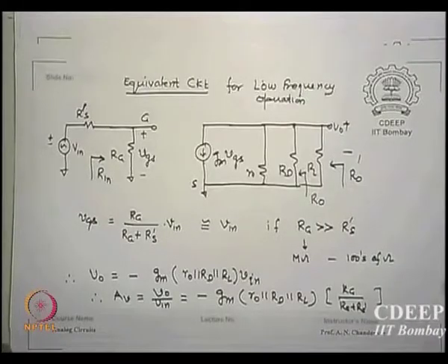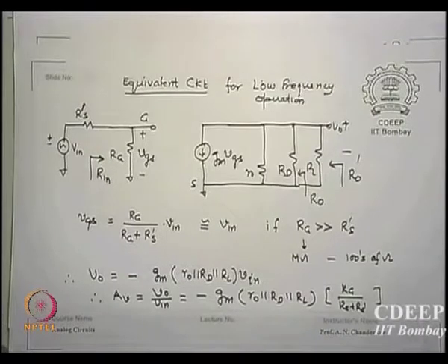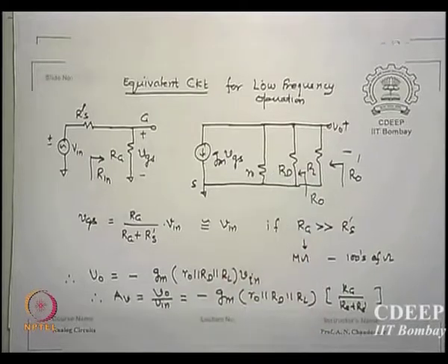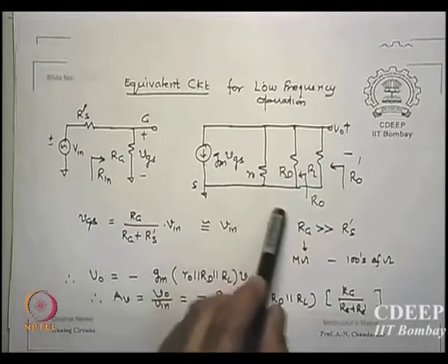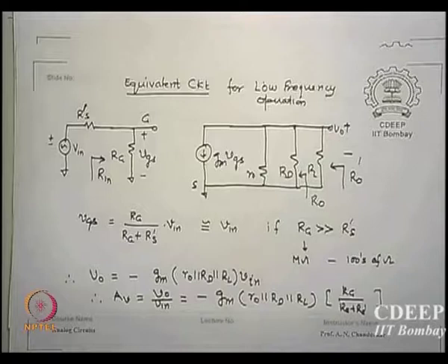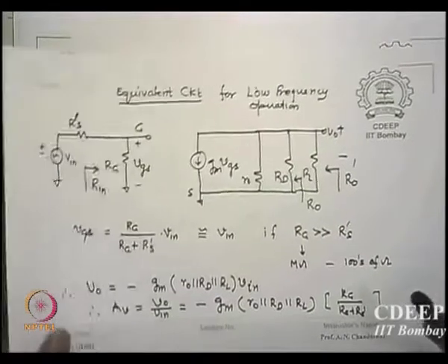Normally RL is not considered to be part of output resistance. Why? It is external, I do not know what people will give me. So normally R0 is taken across RD. Even some people believe you should measure intrinsic R0 also, that is without even the drain resistance. Is that correct? So it will be always R0 in most cases. Okay, so if I do that,